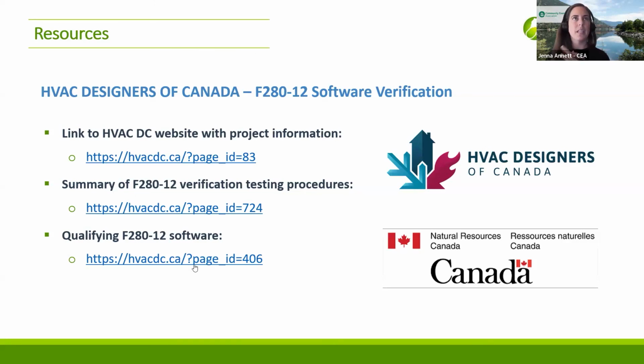Okay, thank you. And what about the case where you're installing a ductless heat pump in a retrofit scenario? Would you do a room by room then? Good point. Yeah, that's true. Because the ductless heat pump can only heat the room it's in, really. It can't go down a hallway, can't go up the stairs, can't go through doors, right?